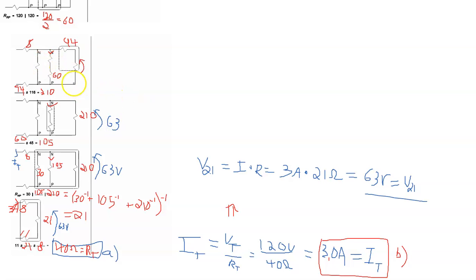Now in this circuit right here, the voltage drop that we're looking for is this one, and we can use voltage division. It is a piece of that 63 volts. In addition, the voltage between N and P is 63, so we can find this current right here. So we still have VNP, let's say, is 63 volts.